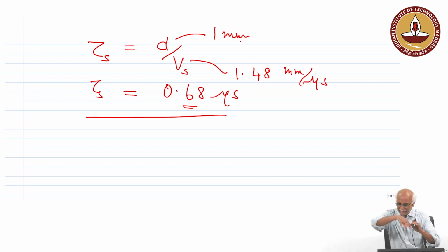So in that region where the laser is interacting, within 5 to 6 nanoseconds where heat is not diffusing out, the temperature increase can be given by the increase in internal energy, m mass into specific heat into delta temperature rise.